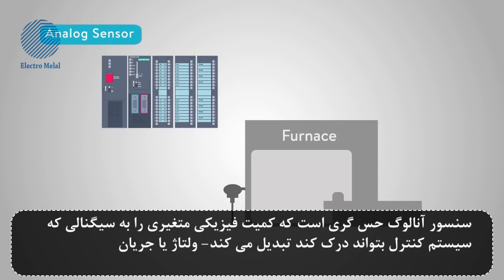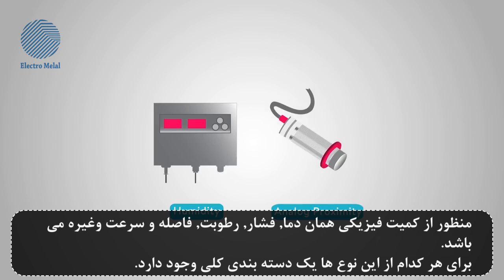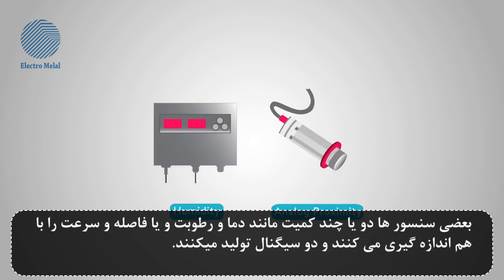An analog sensor is one that converts a variable physical quantity into a signal that the control system can understand, a voltage or current. By physical quantity, we mean temperature, pressure, humidity, distance, and speed, among others. There is a general category of sensor for each of these. Some sensors combine quantities, like temperature and humidity, or distance and speed, into a single instrument generating two signals.